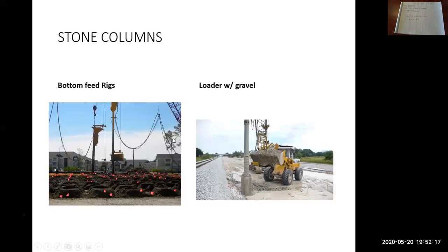So here are the rigs doing it. There's a crane just off the photo here, another one over here. There's a probe. That's what this pipe is. This hopper here goes up and down. This one is down at the moment. So there should be a loader. Can we see it? No, there's no loader there. So this probe gets vibrated into the ground, down as deep as required.